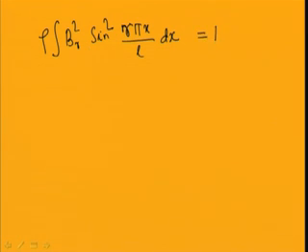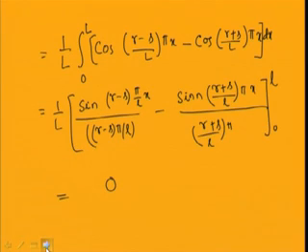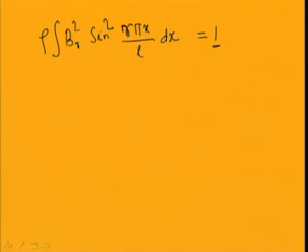So, you have observed that this is equal to 1, and so you can prove that when r equal to s, this integration becomes 1, and when r not equal to s this becomes 0. So, this proves the orthogonality principle of these mode shapes. So, the mode shapes are orthogonal to each other.